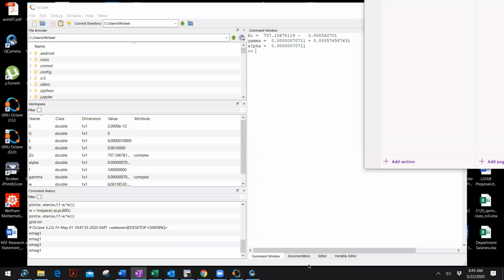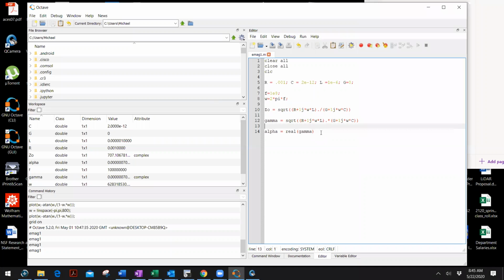So now I come back to my editor. I hope you don't mind me doing this here. I like this because that way you see every single facet of the problem. And I'm just going to say P0, capital P0, is equal to 30. Could be anything, right? And by the way, when you put the semicolon, how many people know what that does? Anyone? It stops it from outputting the result of that line. Yeah, it won't keep reappearing. And that's a thing in MATLAB that gets irritating. If you have like i equals 1 to 500 or something like that, then all 500 values pop up.